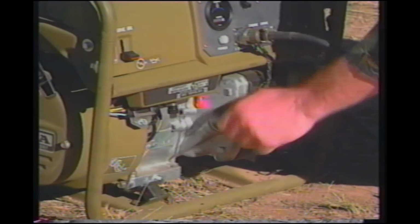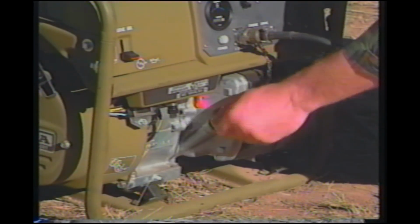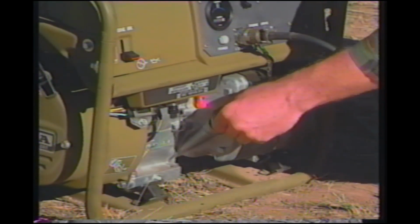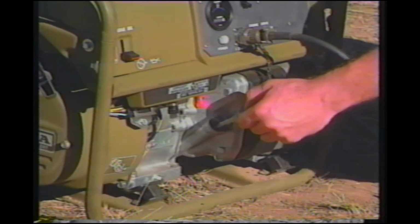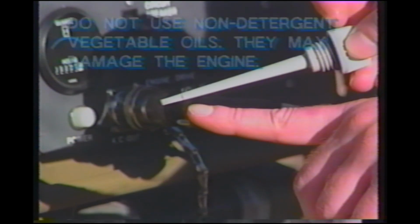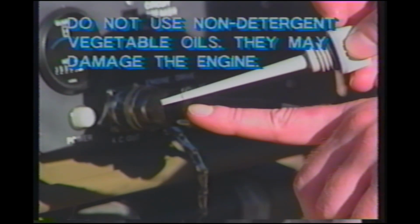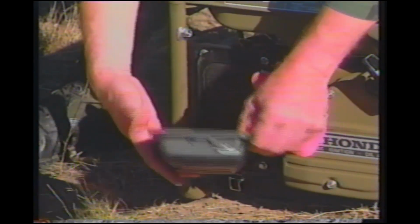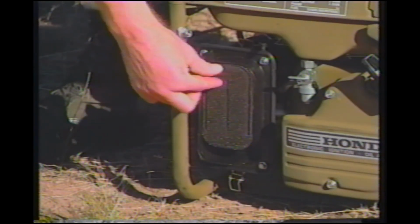Check the oil level by removing the oil filler cap and wiping the dipstick with a clean rag. Reinsert the dipstick in the filler hole without screwing it in, then remove it again and check oil level. If oil level is below the upper level mark on the dipstick, add oil to the correct level as needed. Do not use non-detergent vegetable oils. They may damage the engine. Check the air cleaner. If the element is clogged, wash in a non-flammable or high flash point solvent.